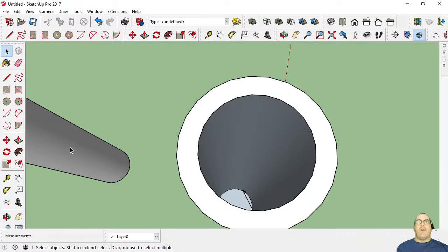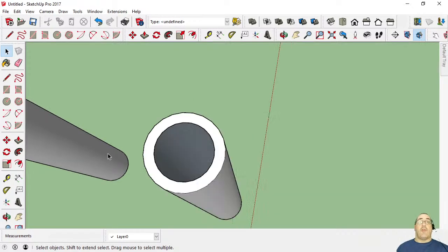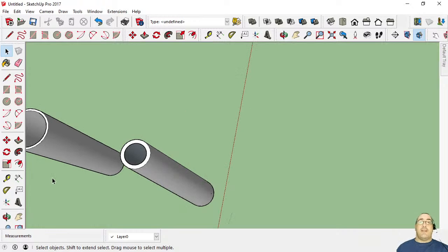Yeah. Now if we did that with this chimney, we wouldn't see that because this is what's called double walled. It has an internal wall and an outside wall. We'd have to cut that hole through both of these. And the quickest way to do that is actually build the shape on the inside and then use the extrude tool to pull it through. But that's by the by.